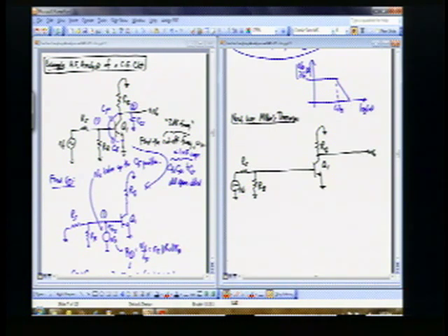All the capacitors I need to care about, I'm definitely going to need to care about this capacitor here, which is C pi. Okay, I'm definitely still going to need to care about CCS. But for C pi and CCS, I didn't have to memorize any formulas. Right? To get the driving point resistance, I just had to get the resistance at these nodes. Right? This was node 1, that was node 2. As long as I can get the resistance at those nodes, which is easy to do because it's all resistors in parallel, I don't have to memorize any equations. The capacitor I had to memorize equations for was this one. Right? That was C mu. Okay, so that's a problem capacitor for me.